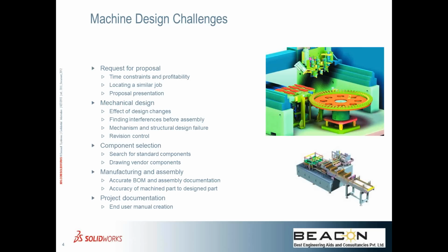A couple of reasons why I see this is important. One is for visualization aspects, as well as BOM related aspects, where you want to see these components in your designs, even though they are bought out items. Second thing is, if you're going to balance your assemblies or mechanisms, or if you want to have the accurate center of gravity and center of mass, these things can come real handy.